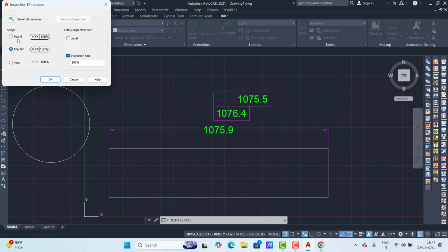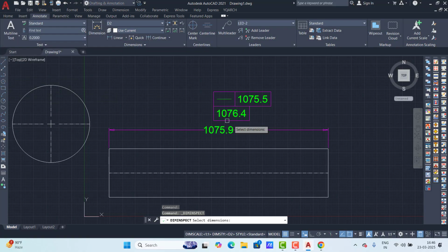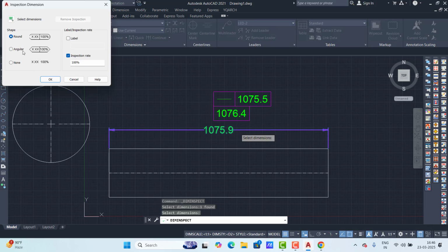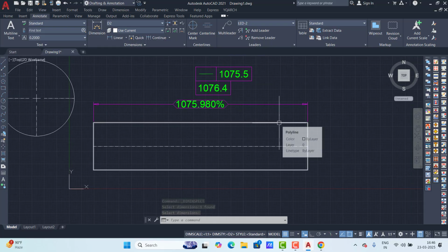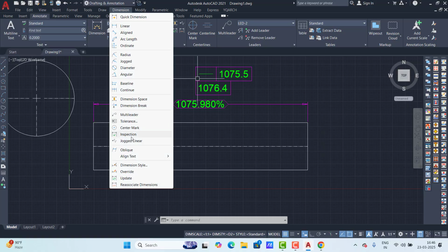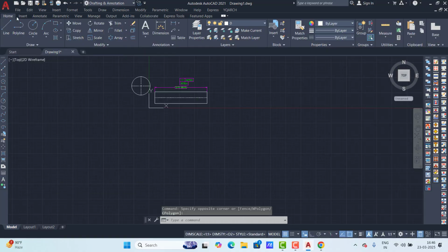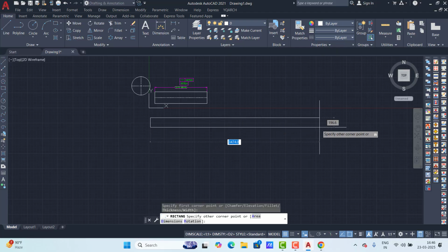Okay. We create here something simple, just 150 square, 200, 150 and 200. Just go here, Fn plus F5 to change direction, then go 400, then change direction and go 200, 400, again down 400 and then we go 150. Okay. Suppose we create a circle here. So EL, Enter, I, Enter, just click here. Fn plus F5 to change direction. That one presents radius 25.